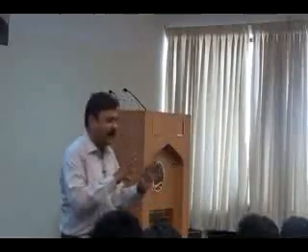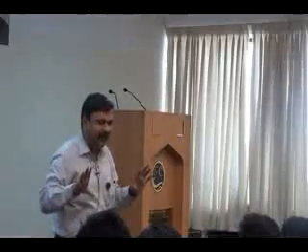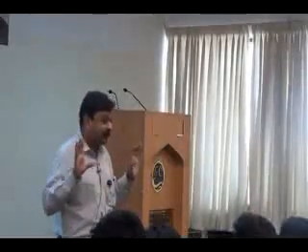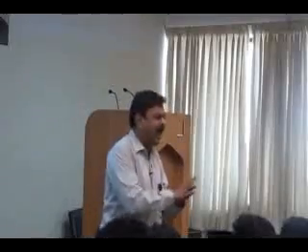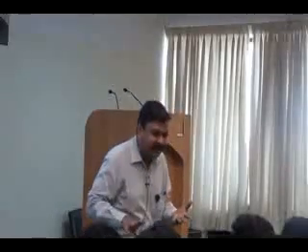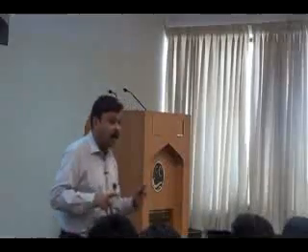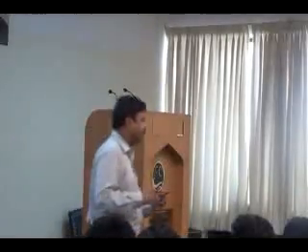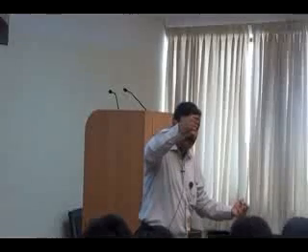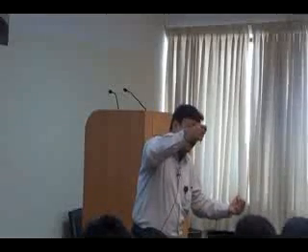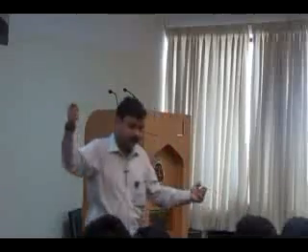Young's modulus is the stress required for unit strain. One way of looking at it is stress divided by strain. Everybody will say stress divided by strain. The other way of looking at it is stress required to cause unit strain. What is unit strain? I have a 1 meter length rod. I will apply a stress that will make it 2 meters.